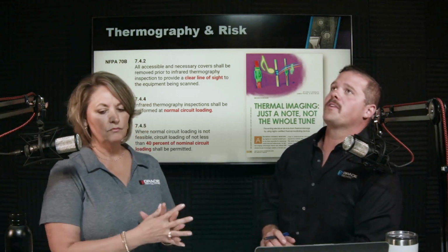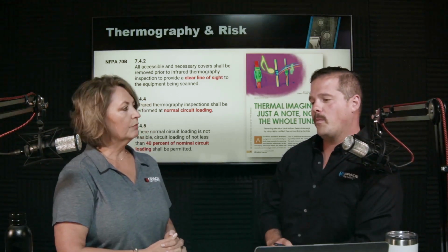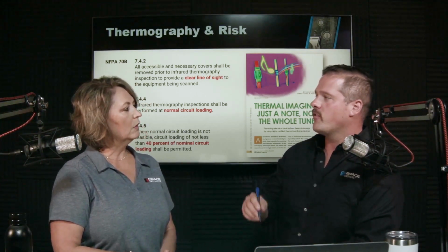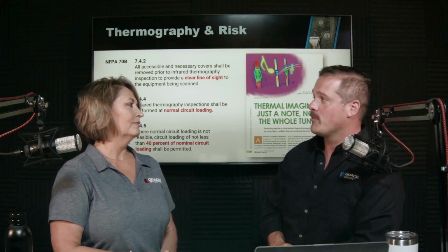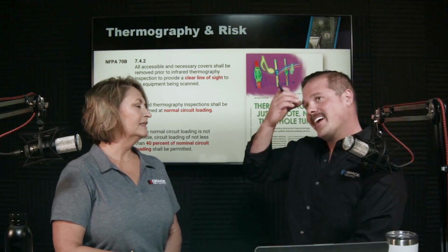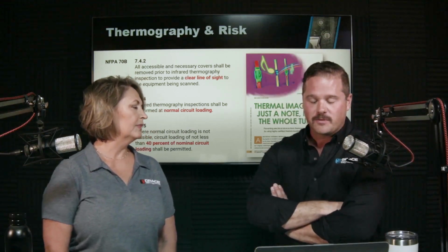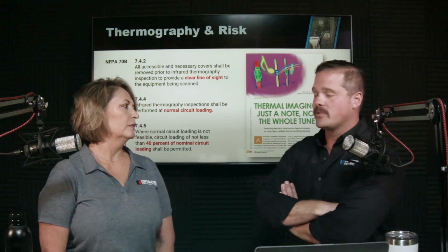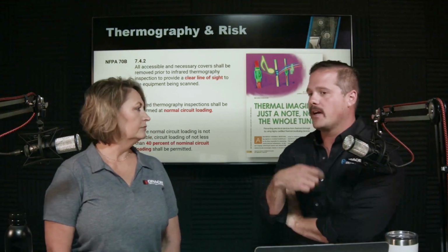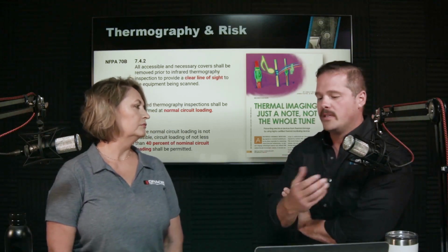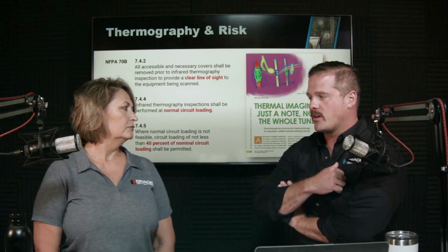One of the comments I've heard way too many times is, we do our thermography every year during our shutdown, and we never see a problem. Yeah. I asked them, well, is everything on during your shutdown? And oftentimes they start to realize that actually that equipment definitely is not under full load. And so you're not going to be able to see these hot spots potentially, as well as then obviously the safety hazard of equipment operating under full load is a massive concern.